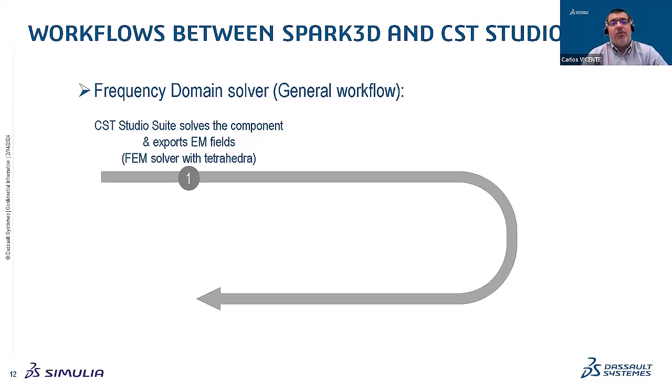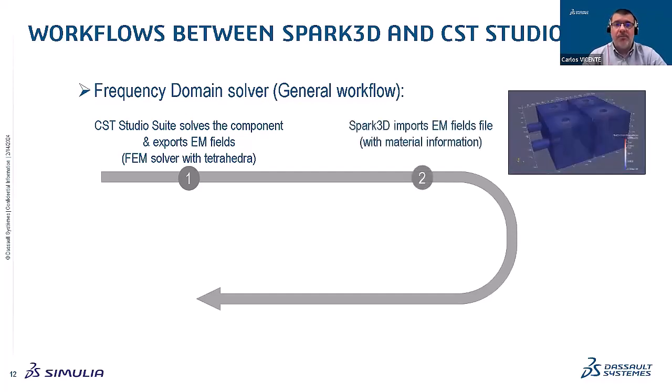Okay, so once you have your design, you can spend any amount of time doing that within CST, depending on the complexity of your component and the needs you have. Once you are done, you can just export these fields to SPARK, and SPARK3D will import those fields through a file, including also the material information.